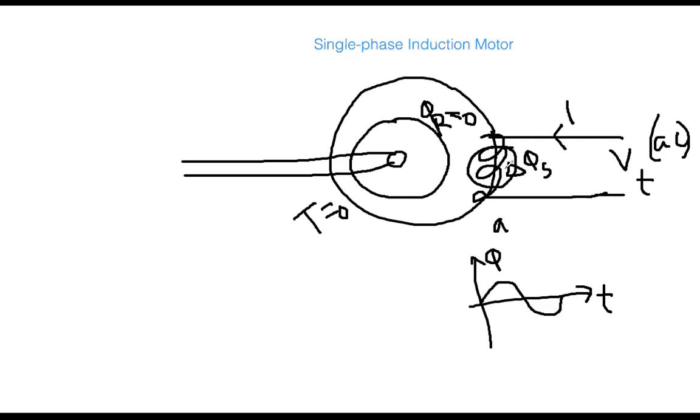because it is not revolving. To produce the voltage, you need relative motion. So this is just changing, but it is confined here. It is stationary in space, pulsating with time, but stationary in nature. There is no movement. And of course, this is a motor, so you cannot connect a prime mover to rotate it from the beginning. Then it would not be a motor. A motor should get rotation with the help of electrical power. So then what is the thing, why is it not moving and why is the starting torque zero?